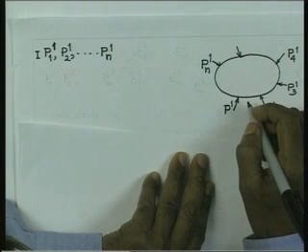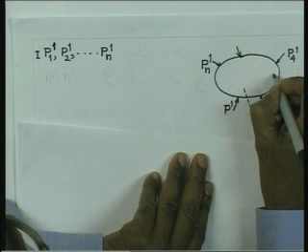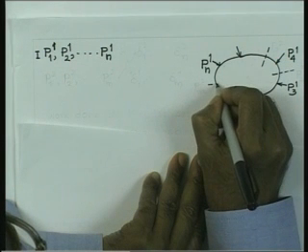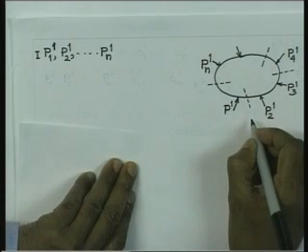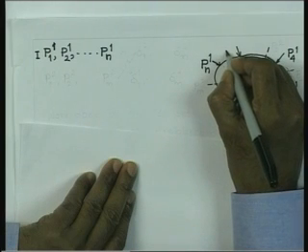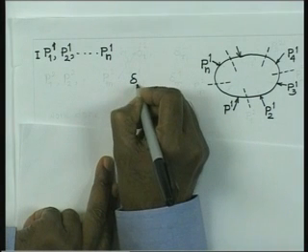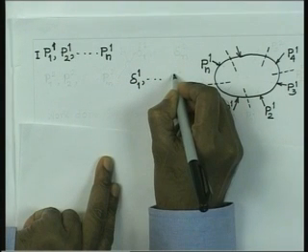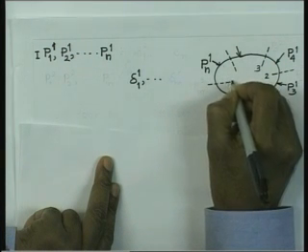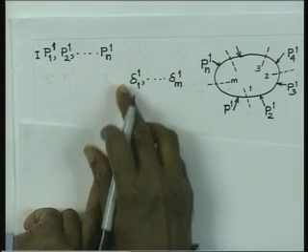Now, if we monitor the deflection produced by these forces, let us say we monitor the deflection produced by these forces along these lines. So, let us consider that this is direction 1, 2, 3, and let us say we consider that m such directions we are trying to talk about. So, this is 1, this is 2, this is 3, 4, and let us say this is the mth direction. So, we will have the deflection produced by the first set given by delta 1 superscript 1 up to delta m superscript 1.